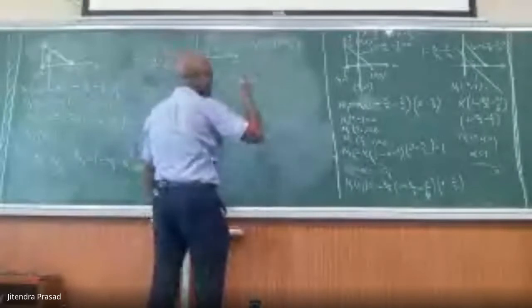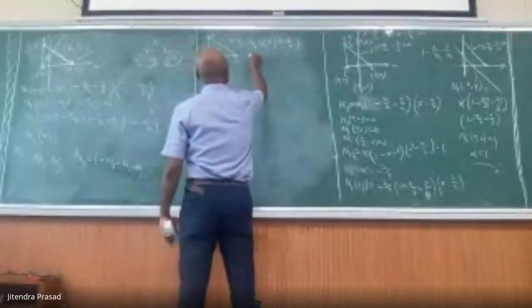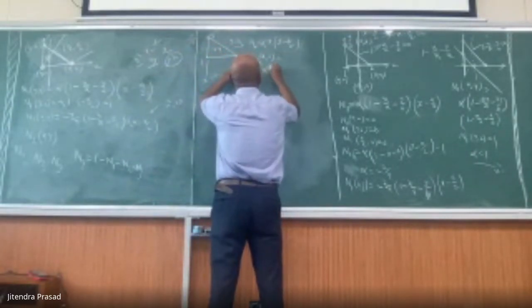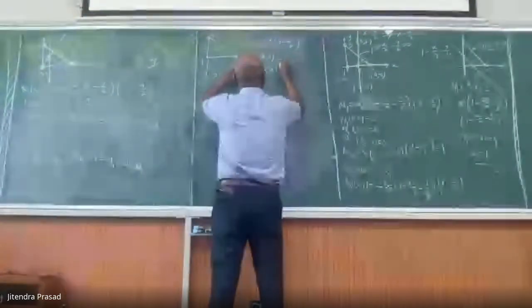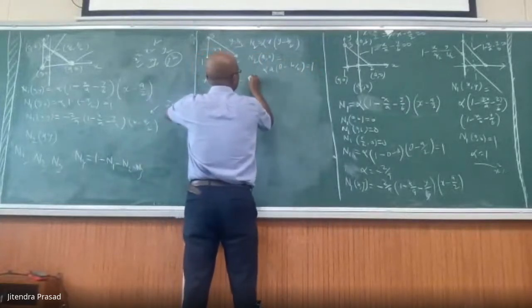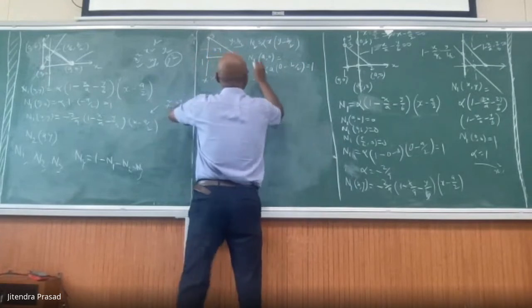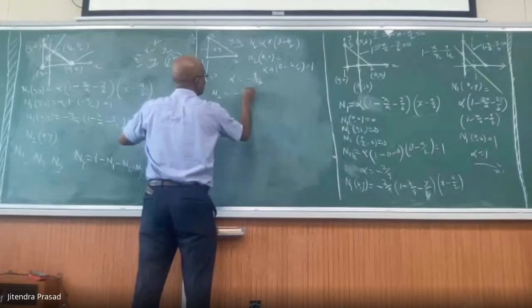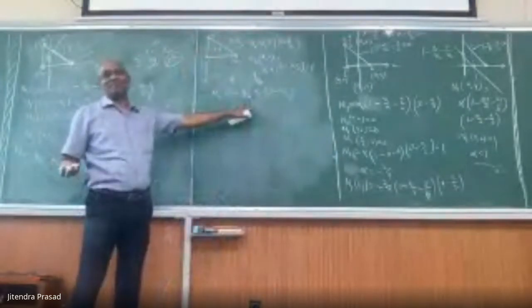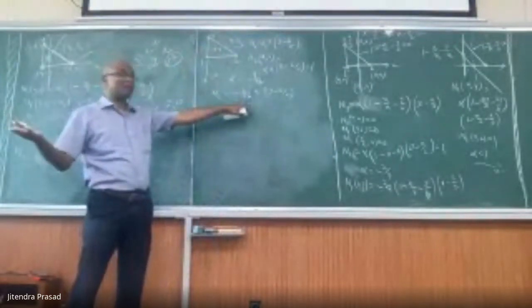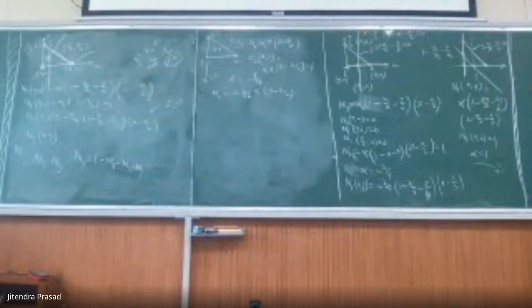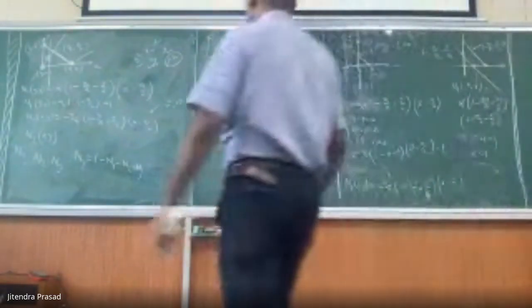Otherwise, it is tricky, that's why I'm saying it's really tricky. So N2 is what? You have A0 equal to alpha, and then you have 0 minus b over 2 is equal to 1, right? So alpha is equal to minus 2 over AB, and hence N2 is minus 2 over AB times x times y minus b over 2. So you have an x term and an xy term. All other coefficients will be 0, like the coefficient for y will be 0 in this case. The coefficient for the constant term is also 0, right? So that's possible. So N2 you have got.